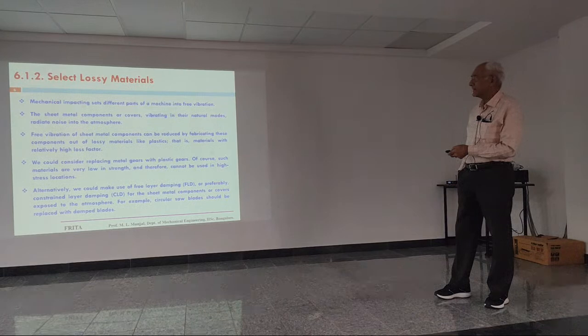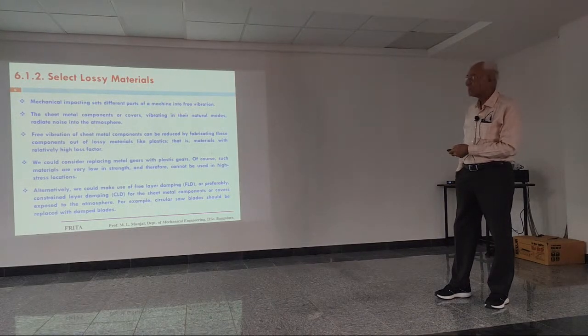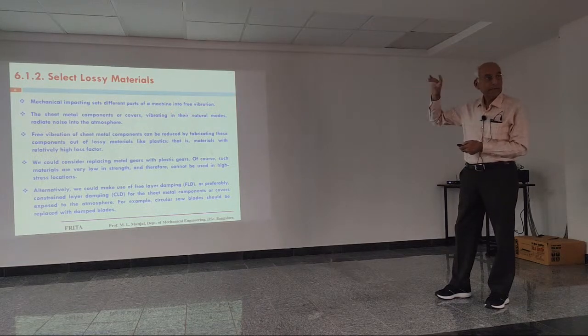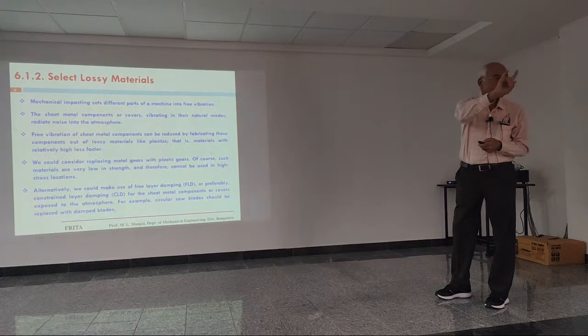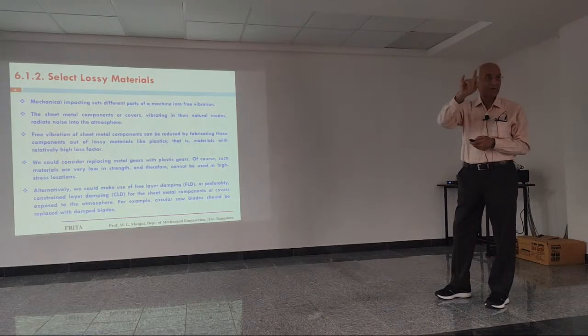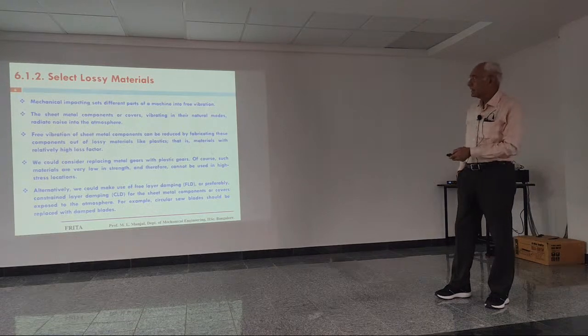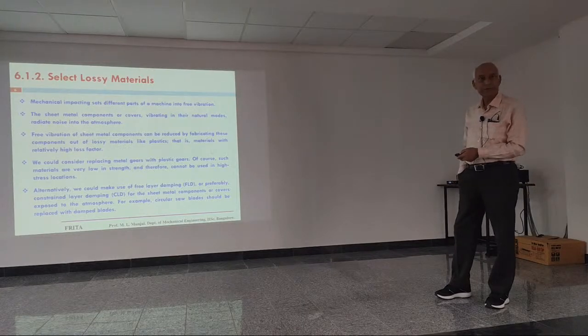mechanical impacting sets different parts of the machine into free vibration. Mind you, all the time I'm talking about free vibration. Damping is not good for forced vibration. I'm talking about free vibration. The sheet metal components or covers, vibrating in the natural mode, radiate noise into the atmosphere.